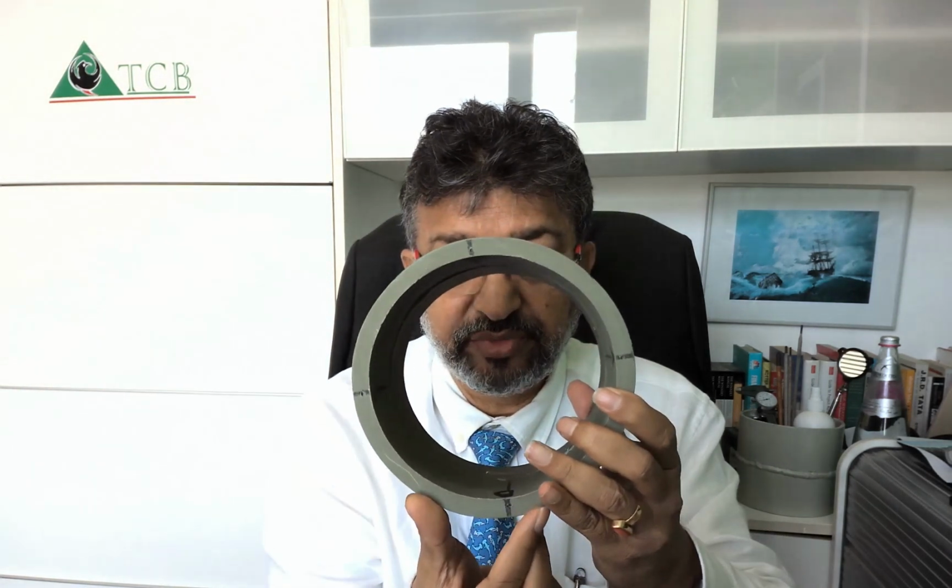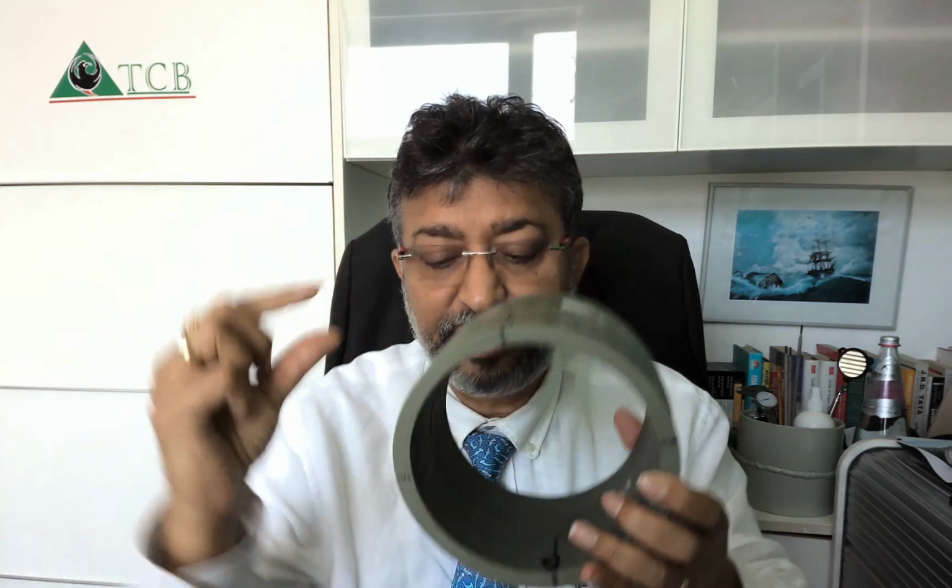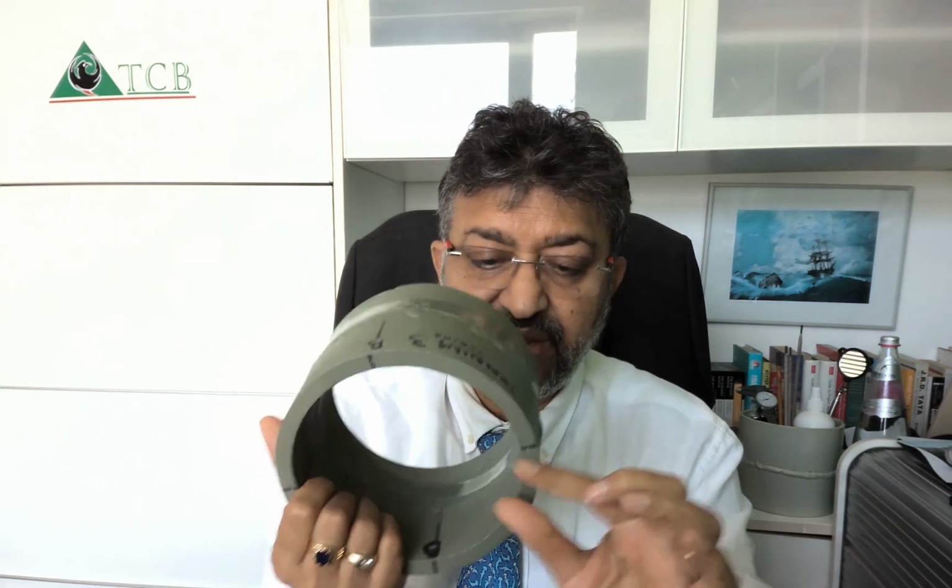So you take one reduced section tensile test sample from the top and one from the overhead position, from this position. And from here you take face bend, root bend, face bend, root bend. Root bend means the root will be in tension. Face bend means the face will be in tension. So you take two root bends, two face bends, and two reduced section tensile tests. Beyond a certain thickness, where it is possible, instead of face bend and root bend, you can do side bend tests as well.